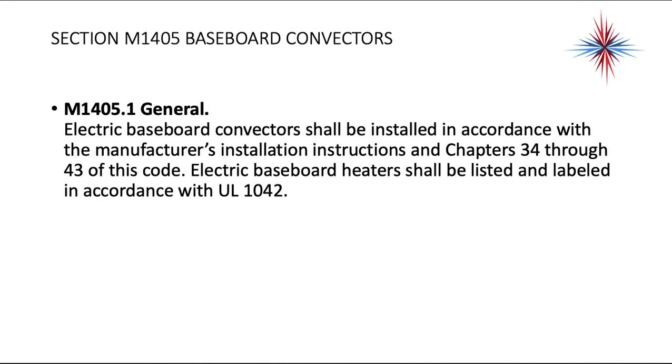Electric baseboard has some additional guidelines in 1405.1. Electric baseboard shall be installed in accordance with the manufacturer's installation instructions and chapters 34 through 43 of this code. Electric baseboard heaters shall be listed and labeled in accordance with UL 1042.